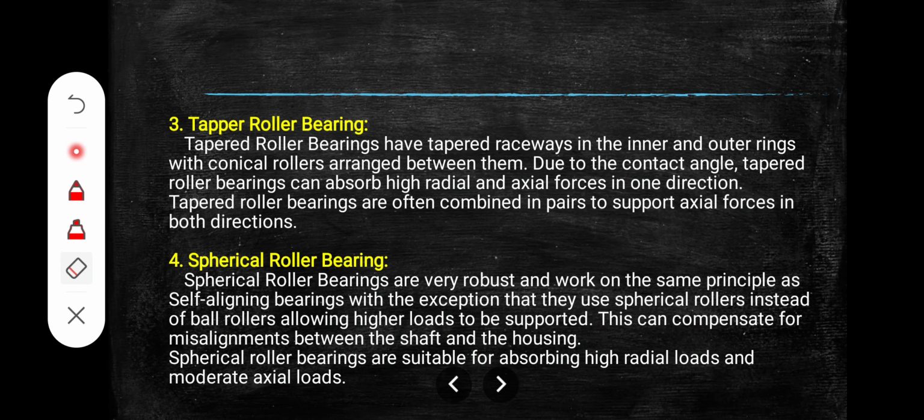As we already discussed, angular contact ball bearing also starts with 32. Angular contact ball bearing 32, 33. But taper roller bearing starts with 302, 303, 313, and this 302 is followed by 02, 03. This is 5 digits. Taper roller bearing is 5 digits, and angular contact ball bearing, 3205, 3305, is only 4 digits. That is the main difference between nomenclature of taper roller bearing and angular contact ball bearing.